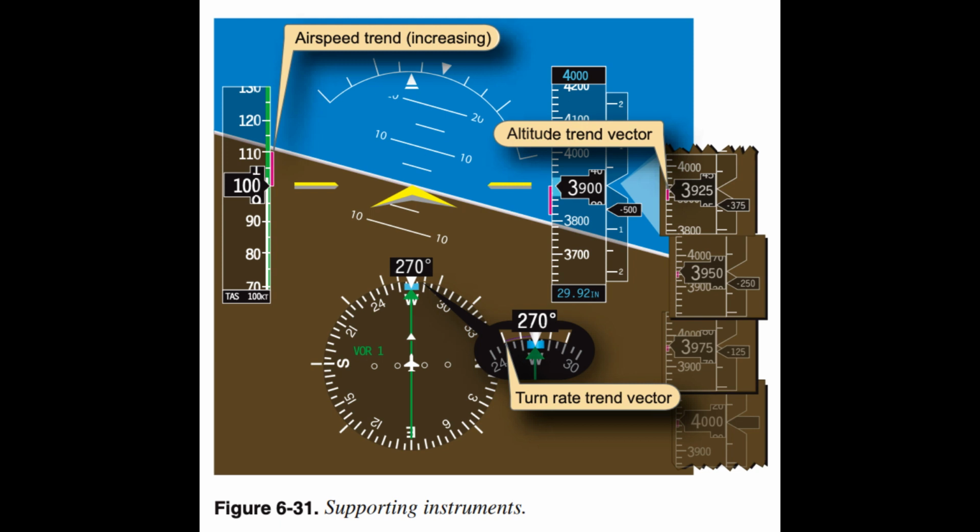Pilots should avoid making large corrections that result in rapid attitude changes, for this may lead to spatial disorientation. Smooth, timely corrections should be made to bring the aircraft back to the desired attitude. Pay close attention to indications on the PFD. An increase in pitch of 2.5 degrees produces a climb rate of 450 feet per minute, (fpm). Small deviations do not require large attitude changes.